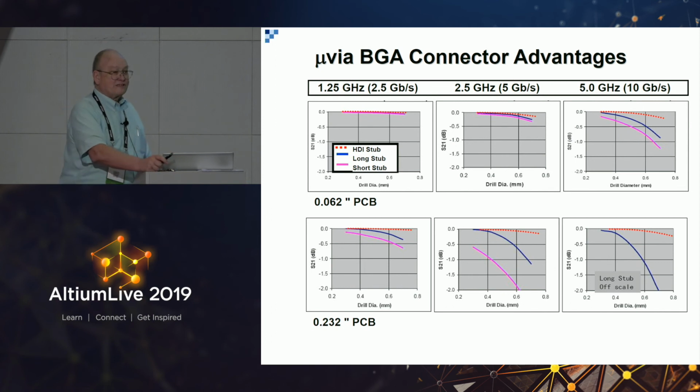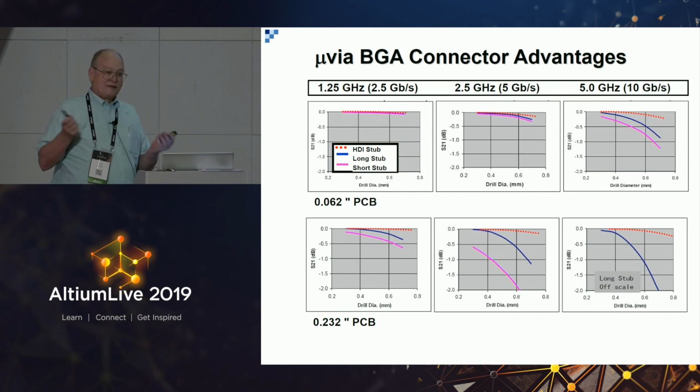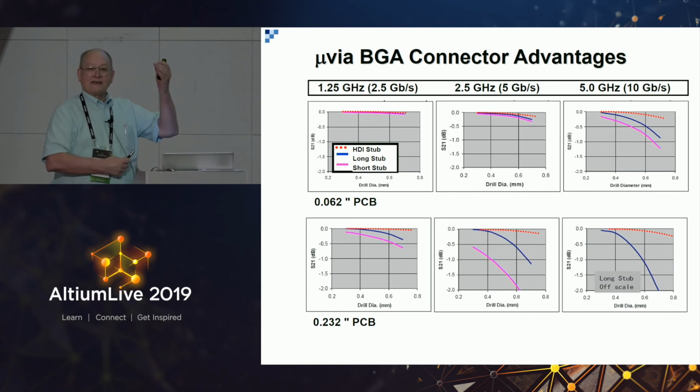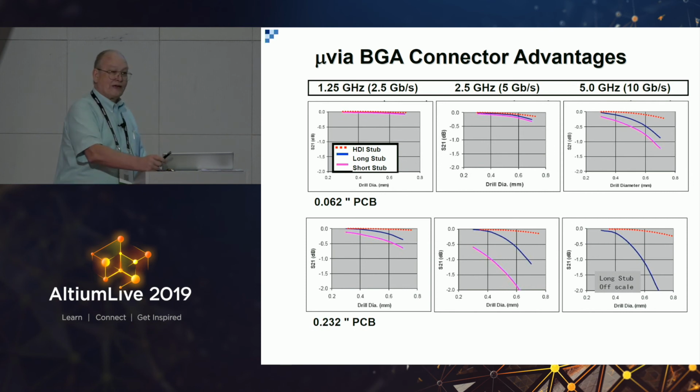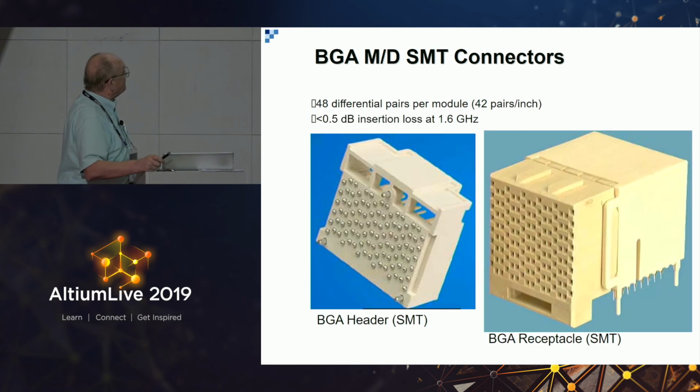So back drilling is not a good idea. Back drilling is very expensive, and very restrictive on design. And what you're trying to achieve is a blind via. Well, if you're trying to achieve a blind via, just design in a blind via for laser. Don't design in a mechanical hole that you then have to back drill out because you're going to pay a lot of money for that. And you're still going to end up with much less signal integrity performance in the long run.